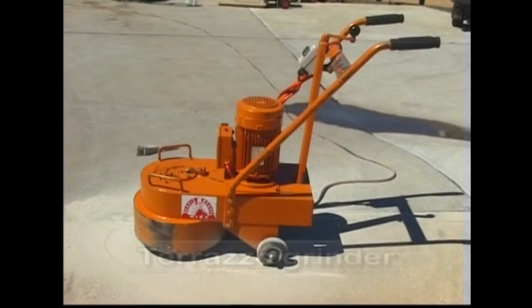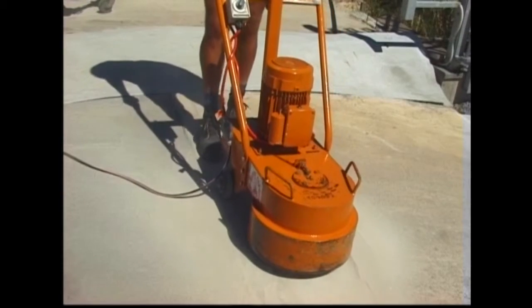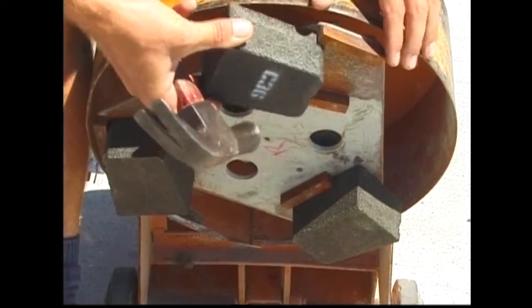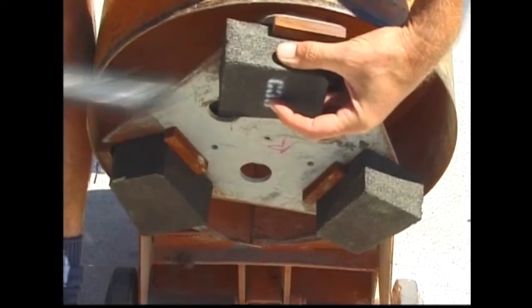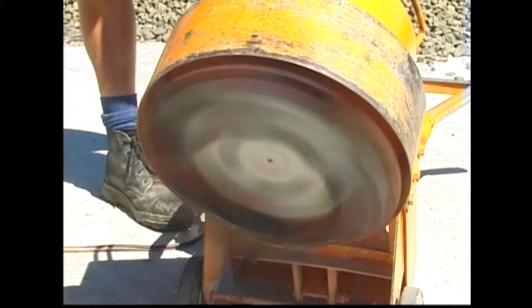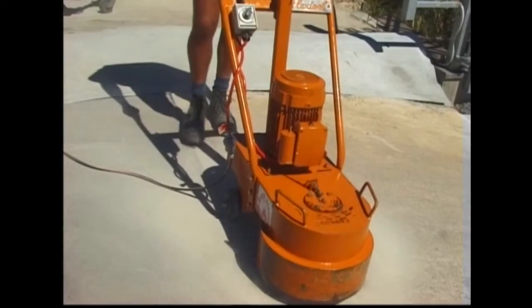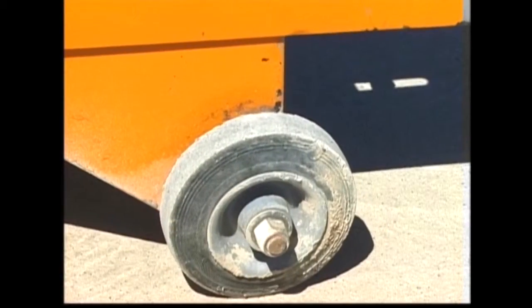Another tool used to finish concrete is the terrazzo grinder. Sometimes called a concrete grinder, it is often used on hardened concrete to repair rough or rain-damaged surfaces. Grinding to a smooth, level surface is achieved by abrasive blocks fitted to the rotating head. Varying grades of abrasive are available for different finishes. Protective equipment is essential when operating the grinder. Height adjustment allows compensation for wearing of the abrasive blocks.